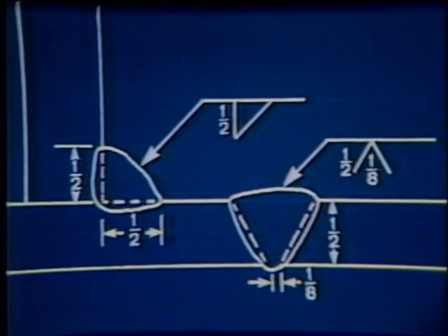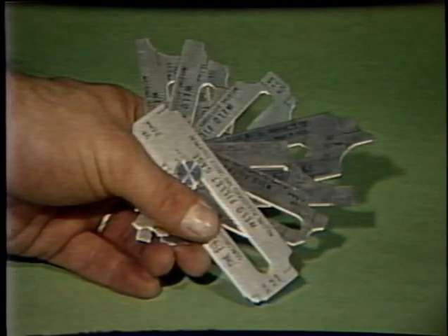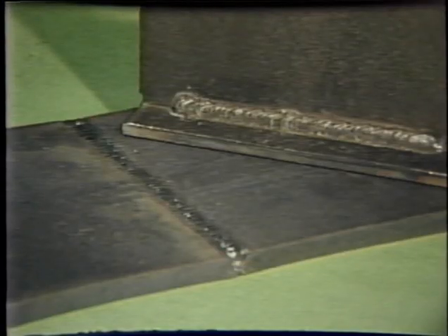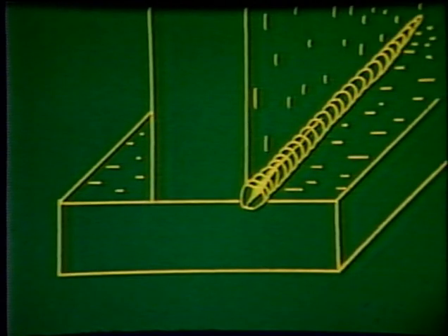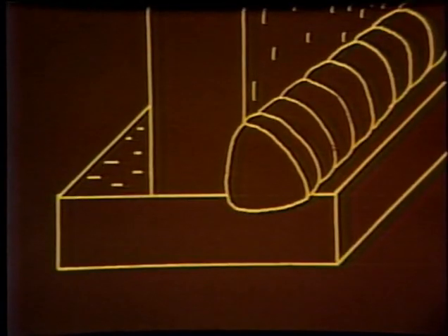Complete welding information should be provided on the engineering drawings through the correct use of welding symbols. Welds that are not the correct size may be detected visually with the use of gauges designed for this purpose, or by comparison with approved workmanship samples. Incorrect weld size is considered a defect, since too small a weld may not support the weldment in service, and welds which are too large might also cause a weldment to fail. In general, the larger the weld, the stronger it is expected to be, but this is true only within sound engineering principles.